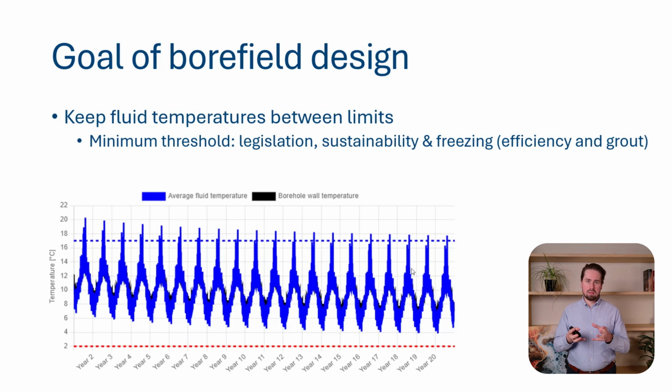Because ice is an insulator, and when there is freezing and there is ice around your borehole, it basically gets insulated from the rest of the ground. So it becomes really hard for the system to extract energy from the ground, and your system performance will drop, your electricity costs will increase. So please stay away from that. It's even possible that your system will fail in the end if it's not able to extract any heat anymore.